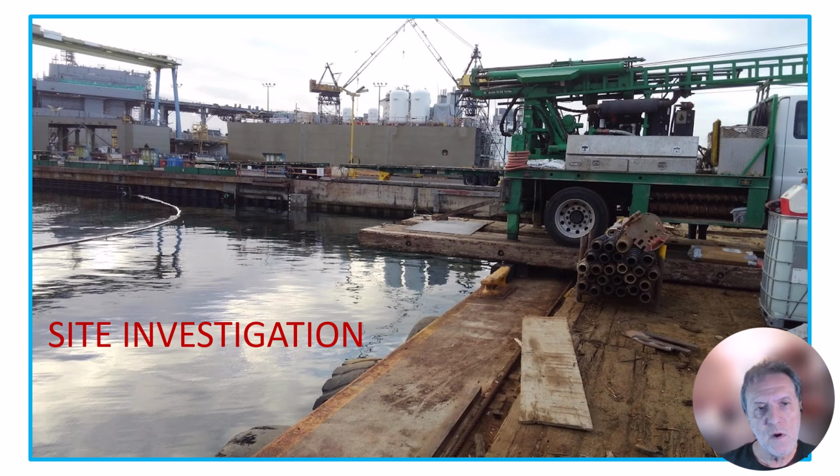Now I'm going to talk about a very important, crucial step in an engineering geologist's scheduled services, and that is conducting and executing site investigations. Site investigations are undertaken and completed to determine subsurface conditions, characteristics of soil, bedrock, groundwater, which may affect construction of a project, give us ways to characterize the soil and bedrock in order to possibly mitigate or improve foundation conditions, such as removal and replacement with compacted fill, or to excavate stiff plastic clays, or to determine shallow groundwater and take steps to mitigate that condition.